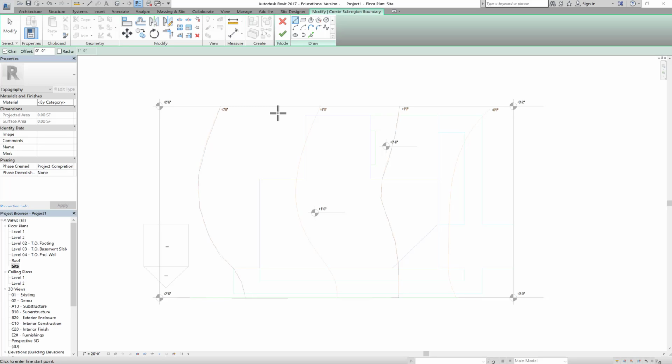When we created our site earlier and started placing points using the underlay, at that time also the screen went gray, meaning that we needed to sketch the profile of the site. In this case, it's again turned gray, and we need to sketch the profile of this walkway.